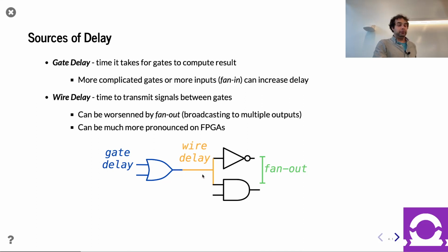And so these tanks are capacitors, right? They're basically holding some amount of charge in electricity, or water in the water analogy. And so it takes time for that water to flow. And if we have more inputs to connect to, because of fan out, that's going to be more tanks to fill. So it takes more time for the water to get to the same water line, so to speak, right? And so in your design, at this individual, very low gate level, as designers, we often aren't looking at this because we're writing high-level statements, things like adds or muxes, and then trusting the tools to do all the logic optimization for us, and we should do that. But we're talking about it today to be aware of where these delays come from, right? Like I said, there is delay from within the gates, the wires, and also the fan out could increase the wire delay, right?